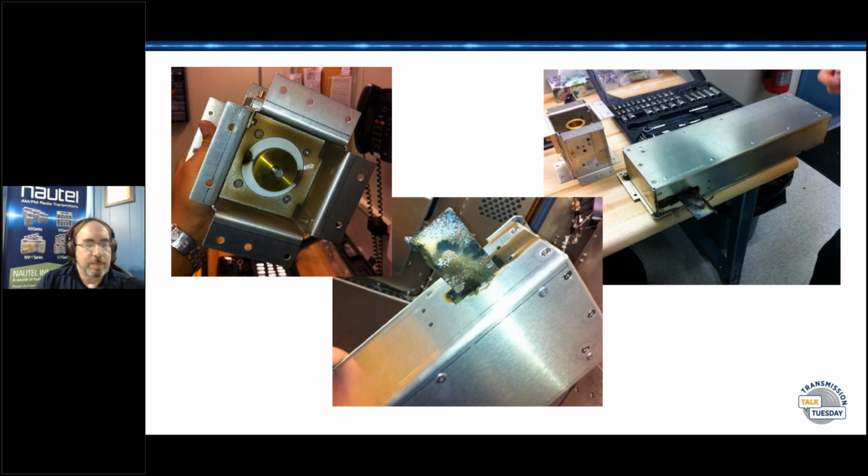My current employer has heaters on all of the dishes in these climates, and that has actually worked fairly well. You put heat tape on the back of it and some insulation on the back of these fiberglass dishes, usually a 1.8 meter KU dish. Also on the feed, there's a little heat tape that wraps around the feed point. It's pretty effective for the most part, but it's another maintenance item to check. You want to make sure that it's actually working.